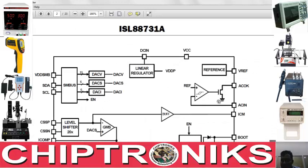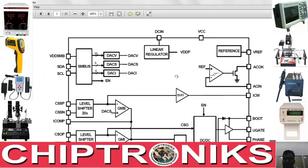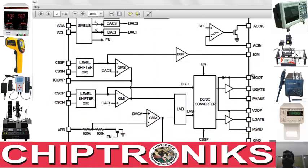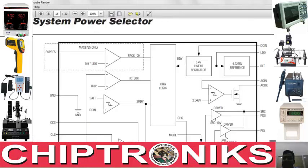And after it gets AC in, it will generate AC OK. If adapter is present, this AC OK would be a high value. If adapter is not present, AC OK would be a low value. Similarly, we discussed in Maxim 8725. So these are DC in, AC in, AC OK. Now we have to check the main outputs from this charger IC. One is the AC OK and another is ICM, that is input current monitor. Similarly over here as IINP.